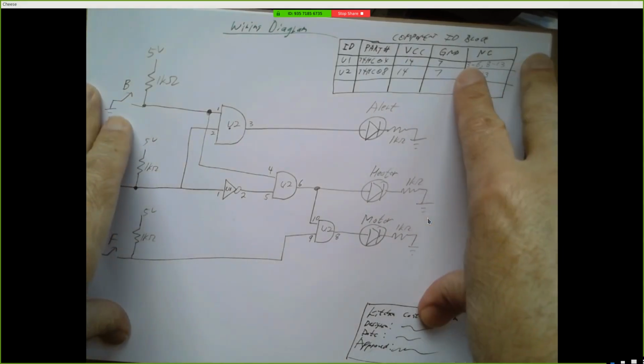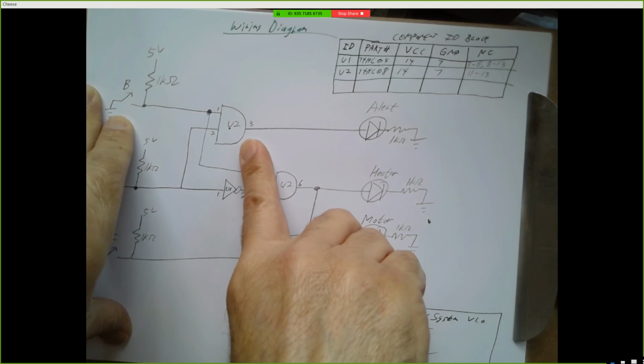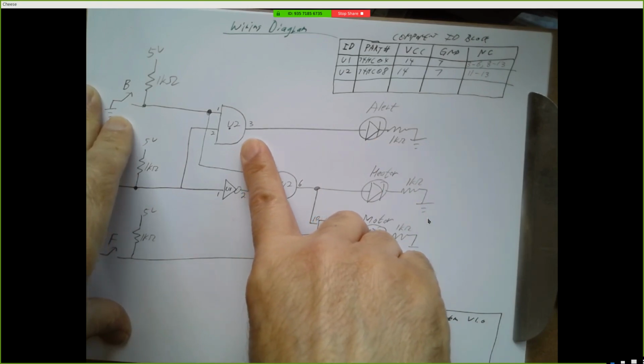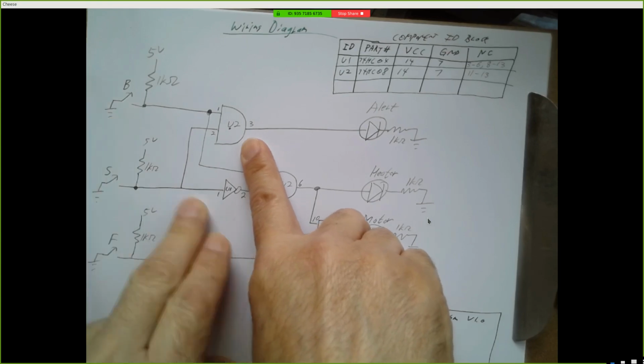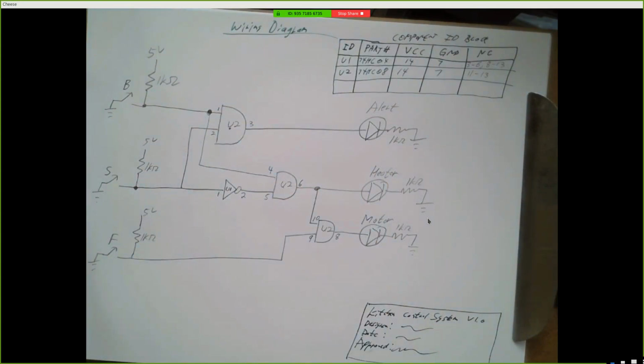Now, if you don't have a wiring diagram, and you want this LED to be on but it's not on, you've got to physically follow the wire on the protoboard and see what it's connected to. Well, it's on pin 3 of this chip. What is that? Well, you've got to pull out the data sheet and see what that pin is supposed to be, and then see where these are supposed to come from, and it becomes a much more difficult task. This is where people usually just rip all the wires out and start over, right? So this lets you actually debug.